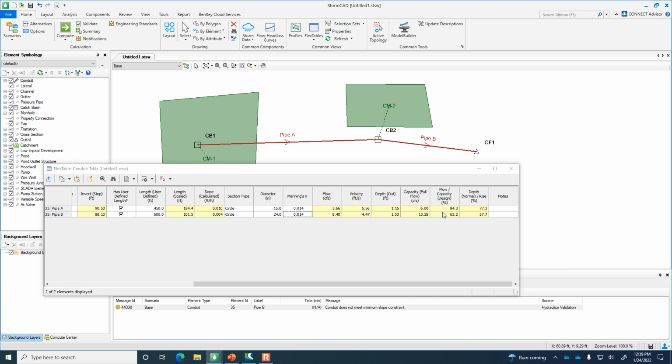Now, if there was a 22-inch pipe available for us to buy, we could try that. But in this case, it's the 24-inch pipe. Like if we just had 15, 18, and 24, 36, then we'd be stuck using this 24. It's as close as we can get to optimal. Okay, so that was step 7, compute. Any questions before we move on to annotate?